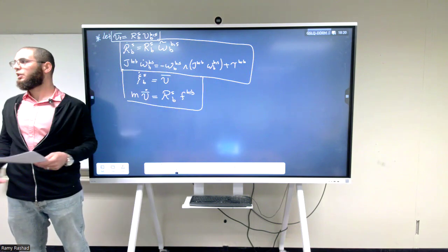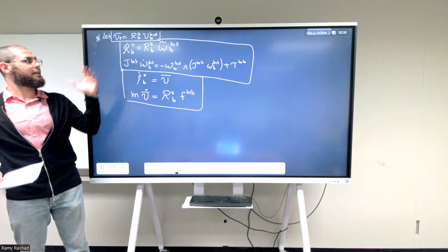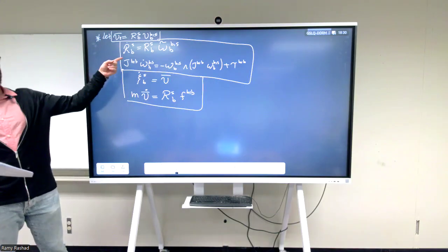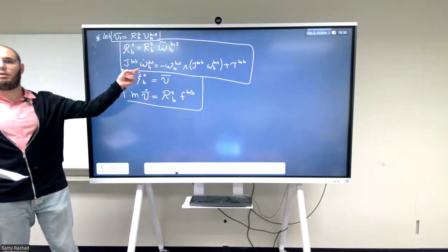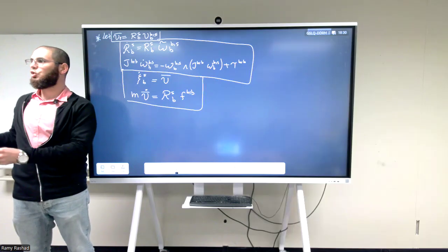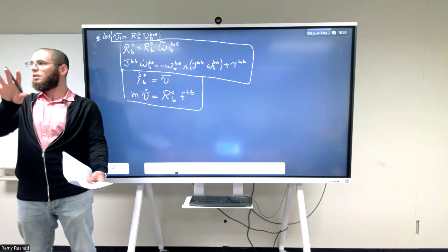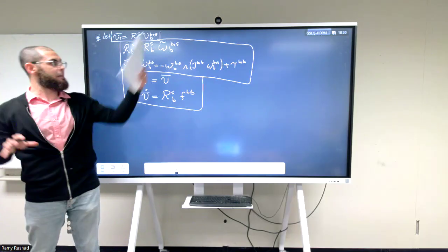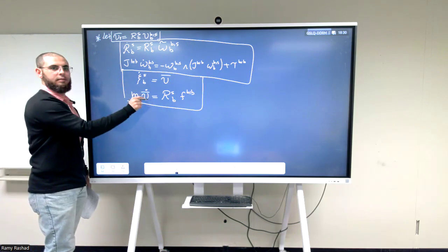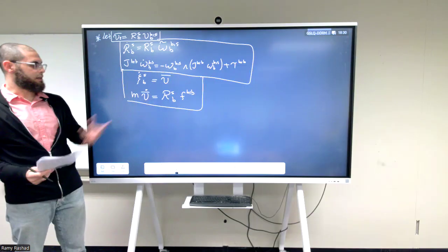They say the equation of motion of a rigid body is simply this: this is the translational part and this is the rotational part. First observation is that rotational is completely independent from translation. You see here? The rotational dynamics only depend on the torques applied. They live on their own. So SO3 dynamics is completely independent from the R3 dynamics. You remember SE3 had an SO3 part and an R3 part. The dynamics on SO3 is completely independent from what happens on the R3, but what happens on the R3 depends on the SO3.